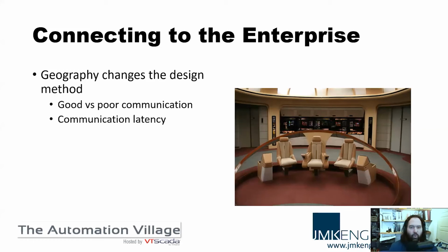So what I recommend to do is use the existing communication network, so our TCP/IP Bell TELUS network. And the piece of equipment that I prefer to use for the RTU is something like a SEL RTAC. I'll get into specifically why the RTAC is attractive to me later on in the presentation when we give a couple of examples of how you would set this up. So the RTAC is a piece of equipment that would connect just before the firewall. And it would connect to all the station controllers, the protection relays, etc.